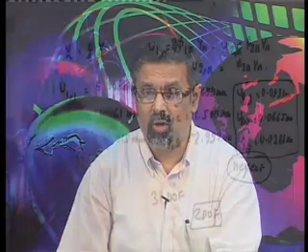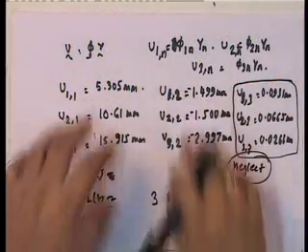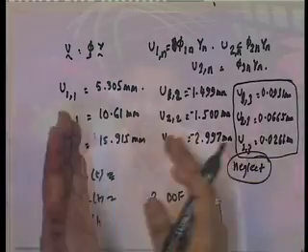So, even though I have taken a harmonic load which is not tuned to the first mode, note that the first mode response is largest. Of course, the second mode response is not negligible, because since it is a harmonic load, this is excited. If you look at any arbitrary kind of load, you will always see that this is the extreme situation in which this contributed significantly purely because it is dynamically more excited.